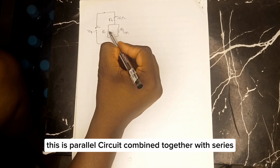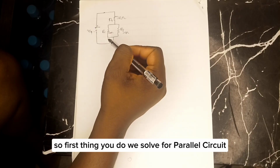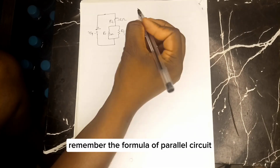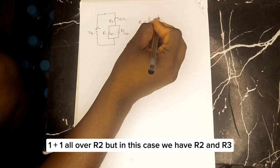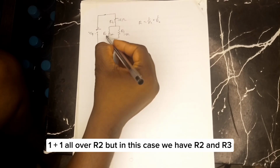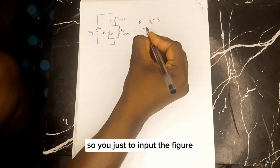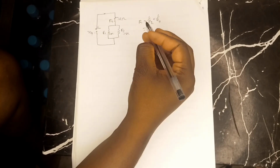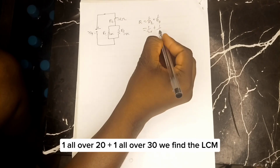So for this, first, this is parallel circuit combined together with series. So first thing we'll solve for parallel circuit. Remember the formula of parallel circuit? The total resistance is 1 all over R1 plus 1 all over R2. But in this case, we have R2 and R3. So here will be R2 and R3. So just to input the figure, R2, 1 all over 20 plus 1 all over 30.